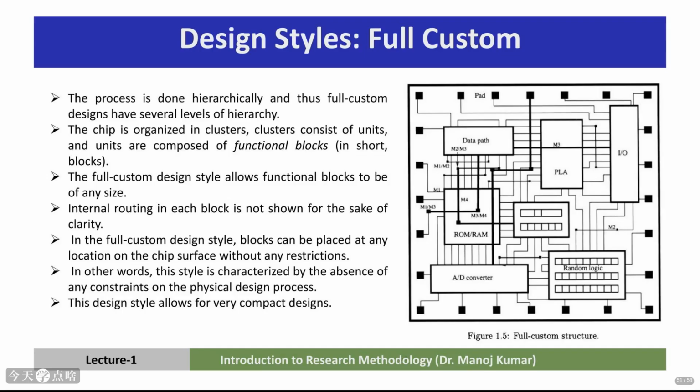Full custom design is typically hierarchical. The chip is organized into clusters, which contain units, which are composed of functional blocks. The beauty of full custom is that you can tailor the size and shape of these blocks precisely. You can place them anywhere on the chip surface without restrictions. This lack of constraints allows for highly compact and optimized designs, achieving the best possible performance and area.